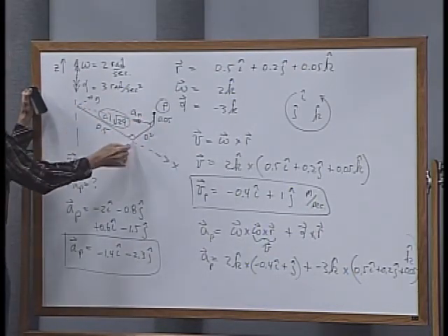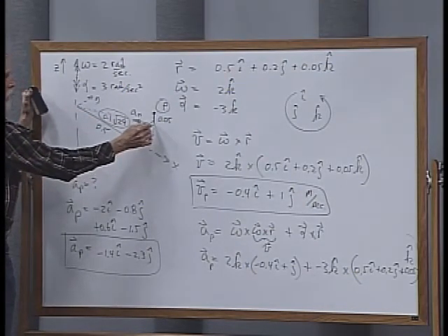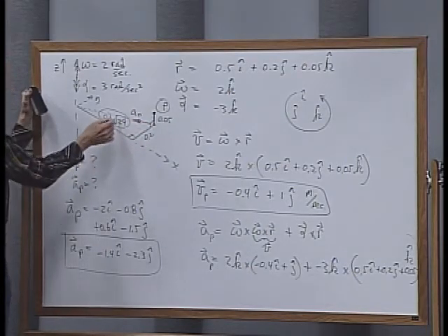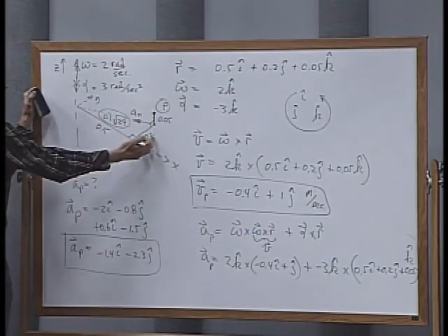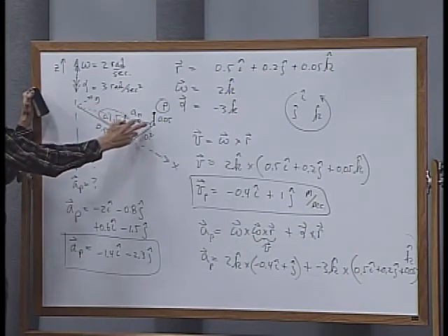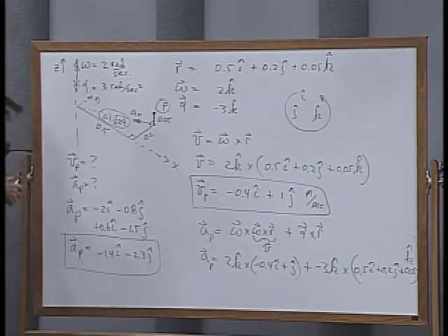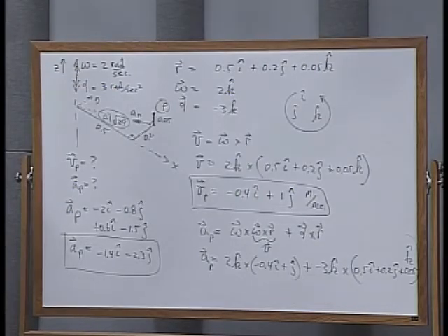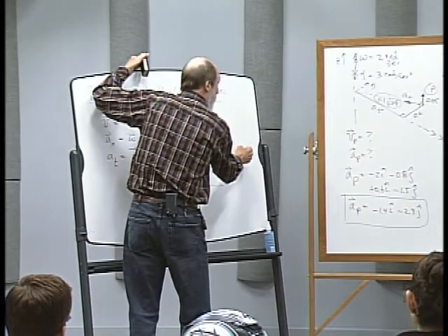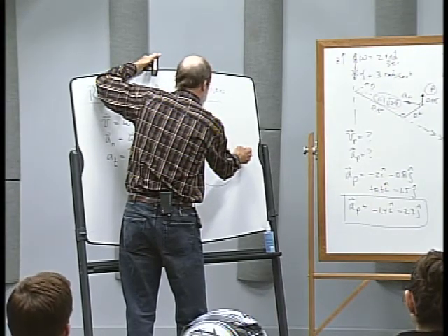If I took the L out of it and just went straight across to this point, down just below point P, this would be our lever arm. I'm just looking at the scaling 2 to 5 here, getting the square root of 29 factor with a 10th tossed in as a multiplier. So if we look down on the top of that, then this lever arm would be 0.1 square root of 29, and our velocity should be pointing perpendicular to that